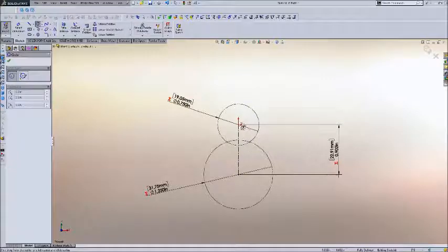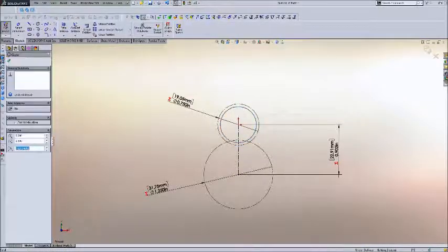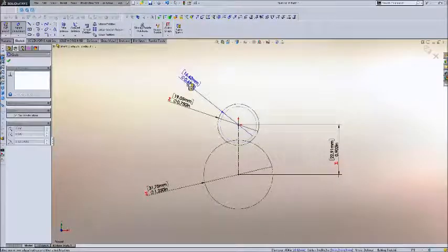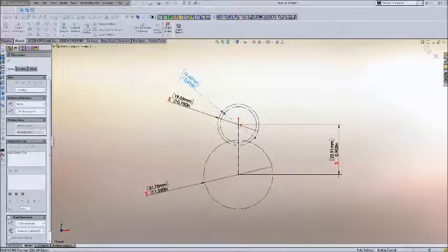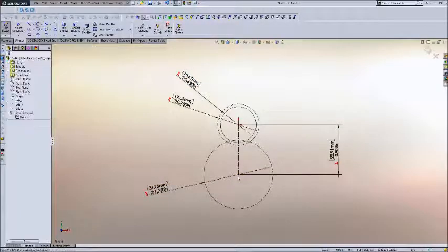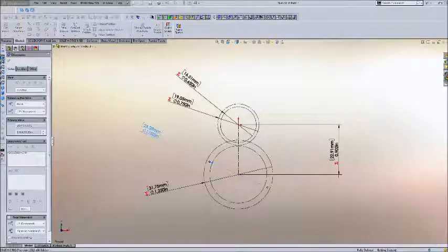Now what do I play with the pitch diameter? Pitch diameter, as I said earlier, is almost the exact same thing as the outer diameter formula, but it's going to be equal to the tooth count, which is going to be 13, divided by the diametrical pitch. So 13 over 20, that's 0.65, less pretty of a number, but it works. And then pitch diameter for the 23-tooth gear is going to be 23 divided by 20.